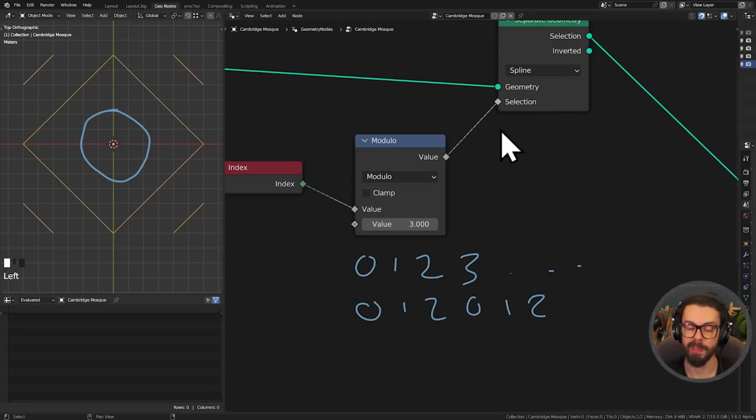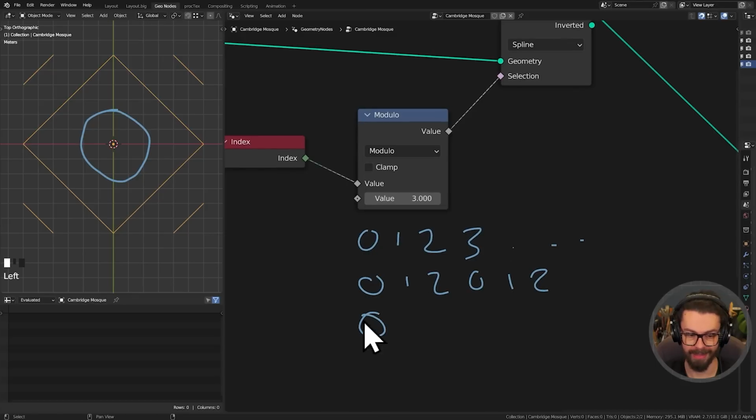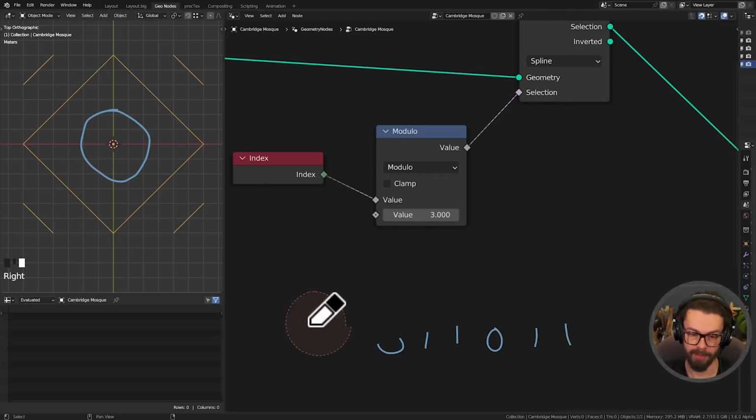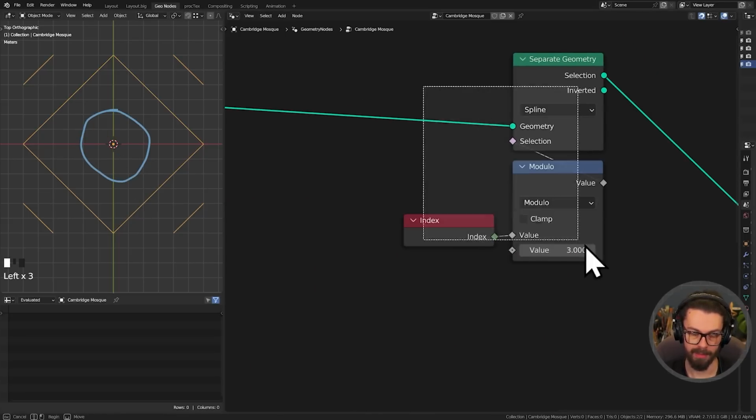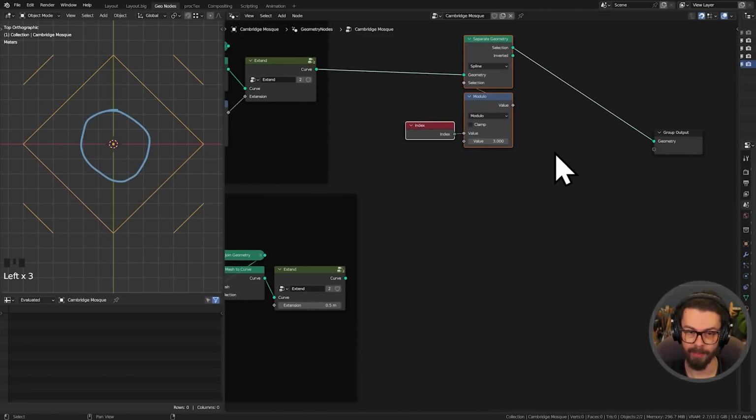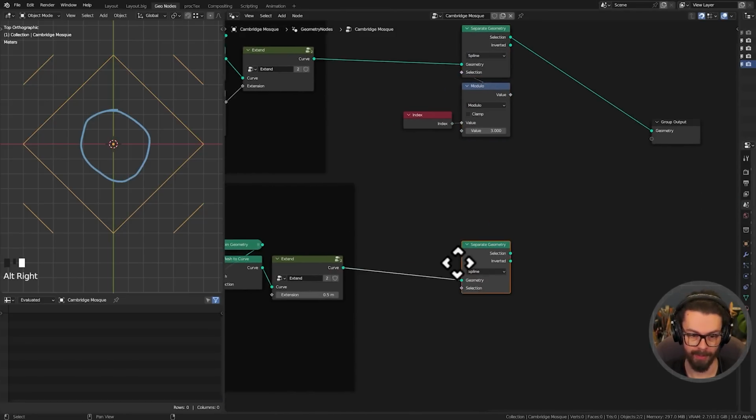And then because we're passing this into a Boolean selection, it's thinking this as 0, non-zero, non-zero, 0, non-zero, non-zero. So that's how we can just use that directly without a compare node. Just saves you a little bit of time there. So this is splitting off the ones that go through the middle. And then we're going to basically do the same thing. So separate geometry down here.